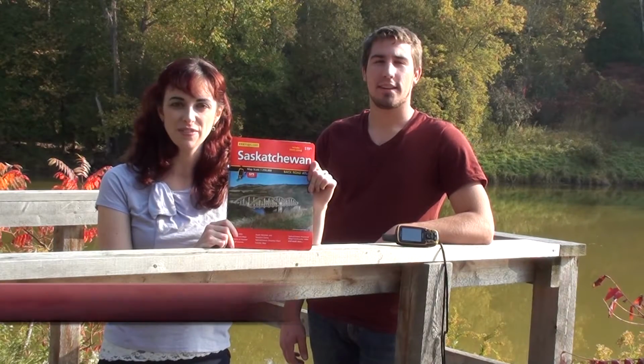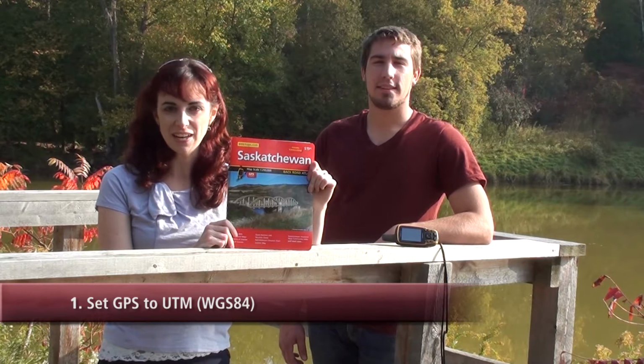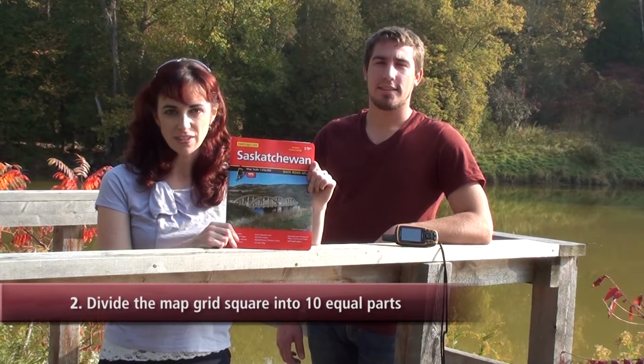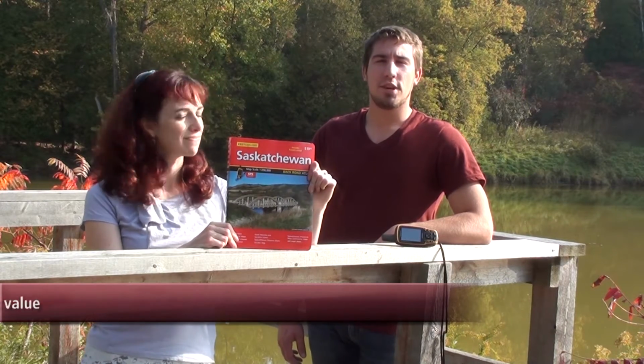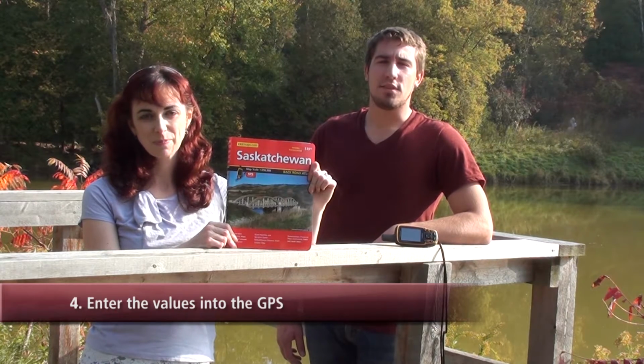Make sure your GPS device is set to Universal Transverse Mercator UTM WGS 84. Divide the grid square into 10 equal parts horizontally and vertically. Determine your eastings and northings value, and enter the eastings and northings value into your GPS unit.